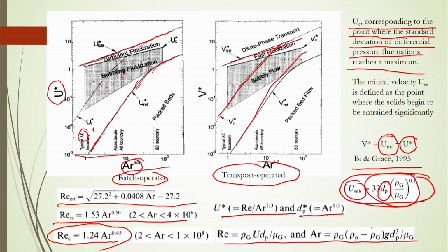That means here the velocity of the gas inside the bed will be so high that you can get the operation of bubbling fluidization. But what should be the minimum? If you consider air and a particle size of 100 micrometer, and substitute here